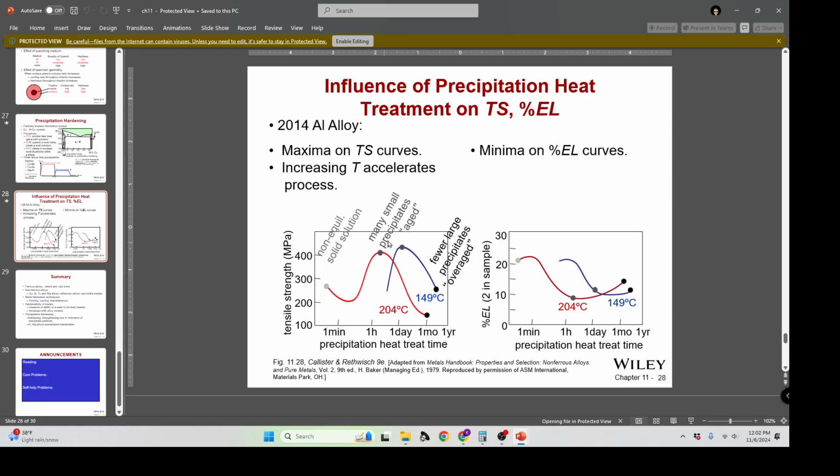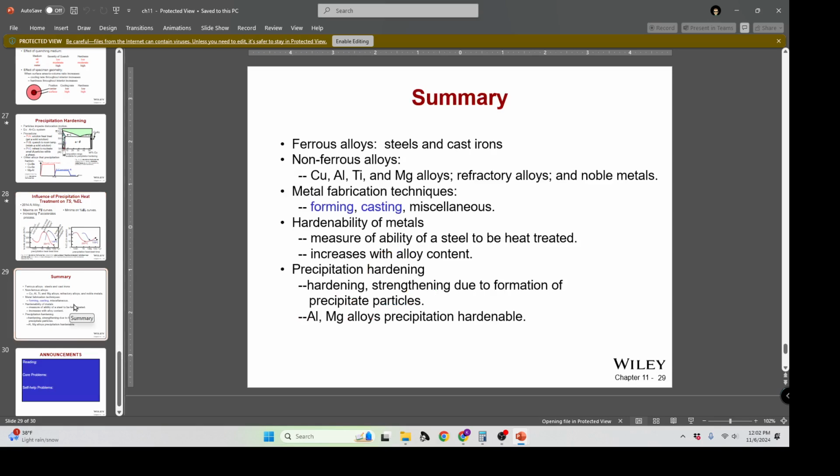You heard the example of aging because of heat treatment, aging the material. That was done for some of the wheels that were being made. That allows for a decrease in the overall tensile strength so that something can be machined again after being much harder. They're aging the material in order to make it easier to machine for some of the last steps, and that's what that curve is telling us about.